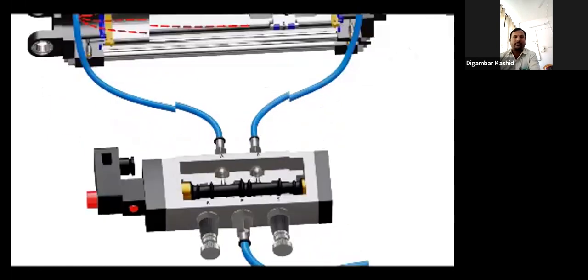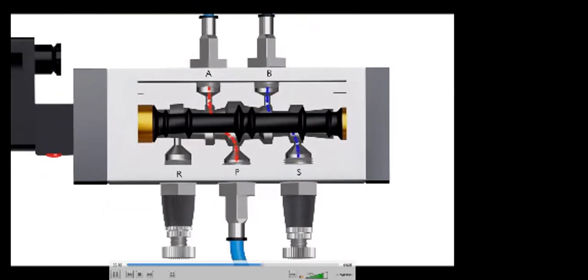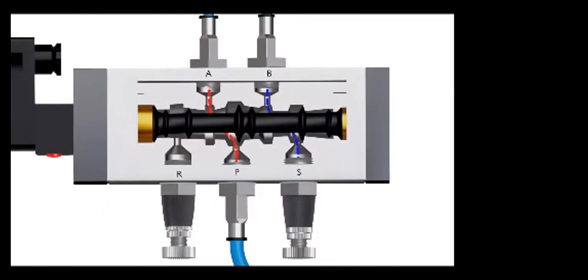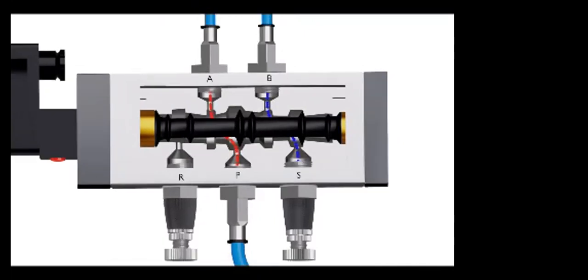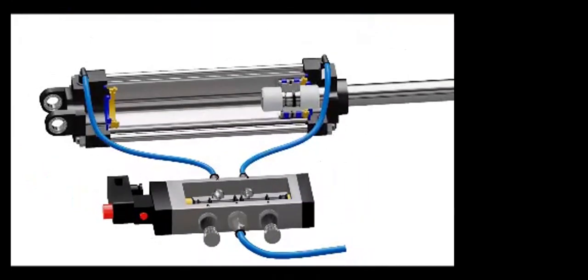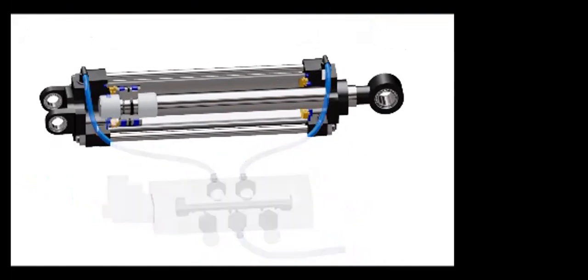The hose reaches the valve. The valve directs this gas towards port S and allows it to escape through a pneumatic muffler. The gas muffler helps to reduce any noise produced during exhaust. The process we just observed is the extension stroke of the actuator. During the retraction stroke, the valve directs compressed air to the head end of the cylinder. This causes the piston to return and the air in the other chamber escapes from the exhaust port R.